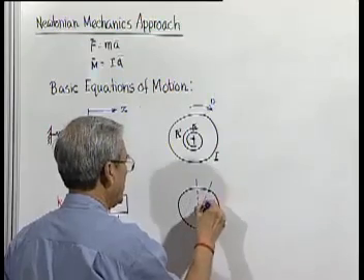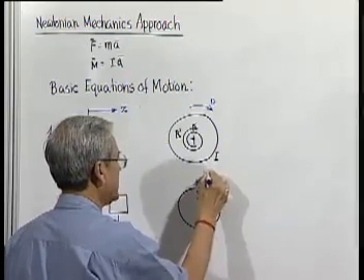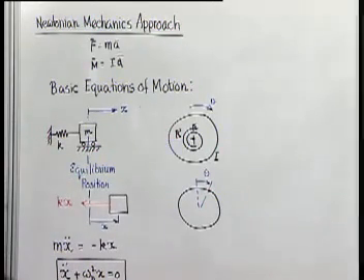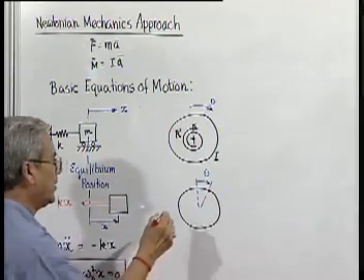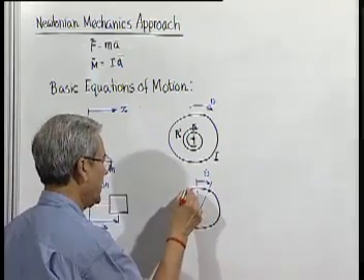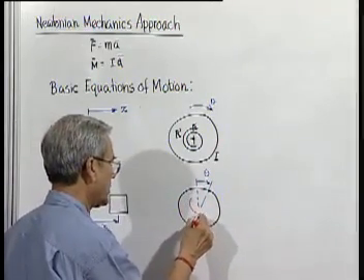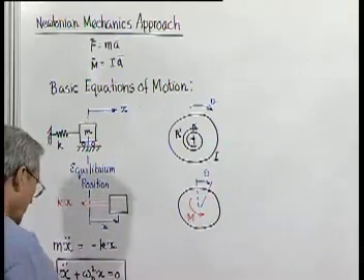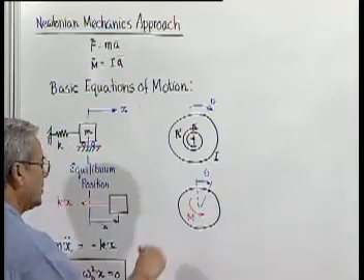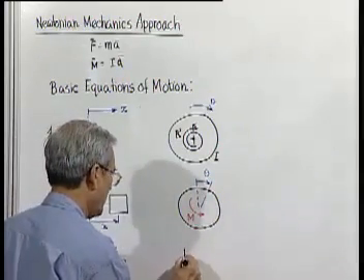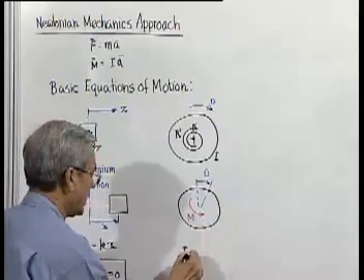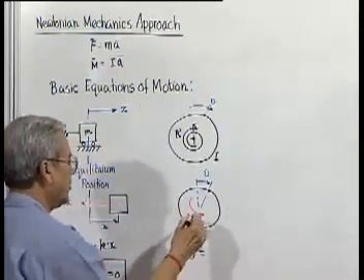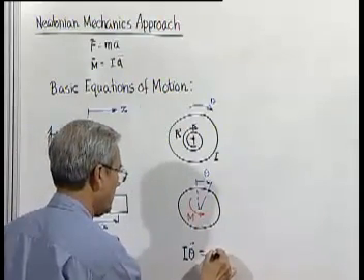Then when the angular displacement is theta, as the torsional spring is now deformed, it will apply a moment in this direction, which is M. And the equation of motion, that means I, moment of inertia, into angular acceleration, that is theta double dot, must be equal to the total moment acting in that direction, which is nothing but minus K theta.